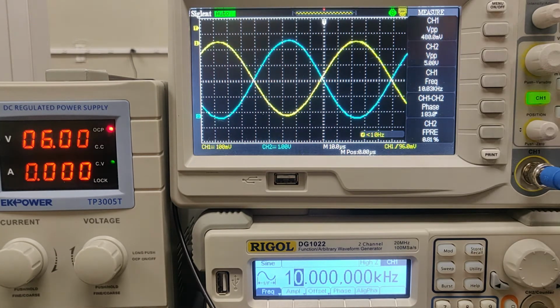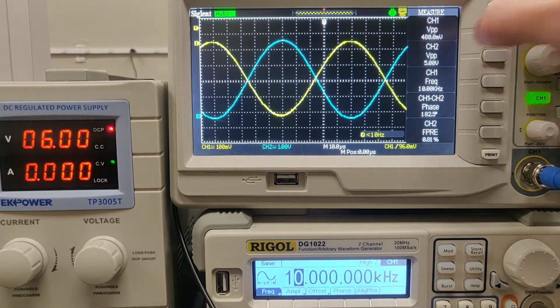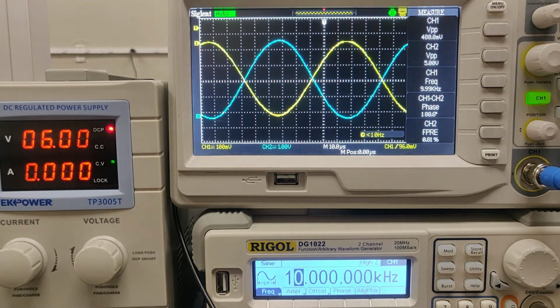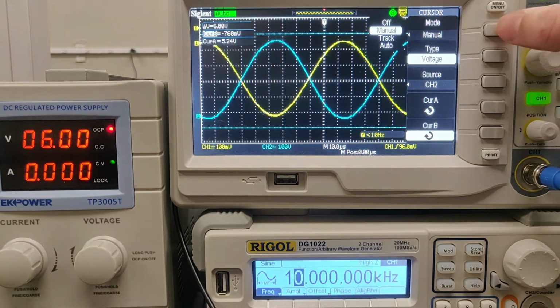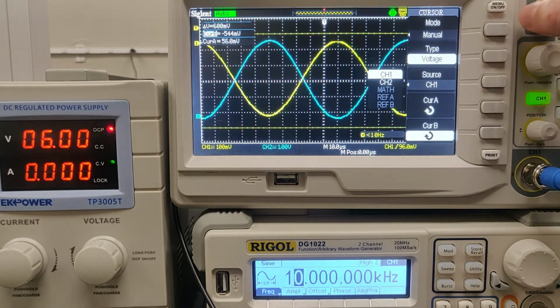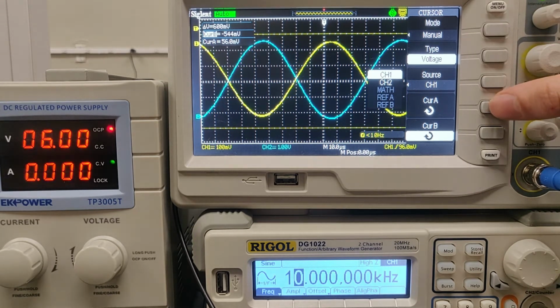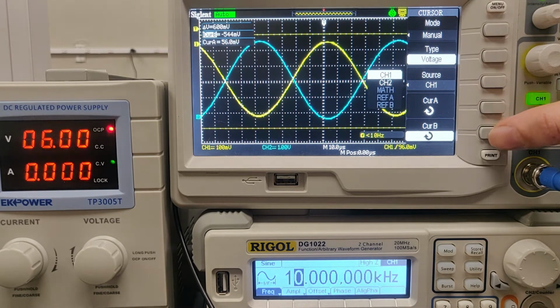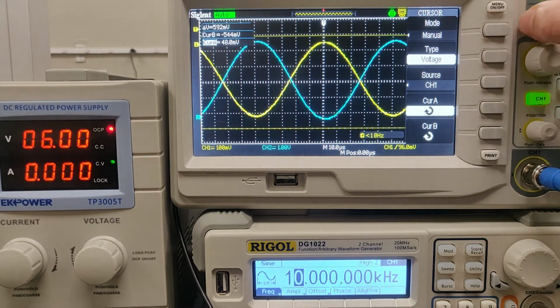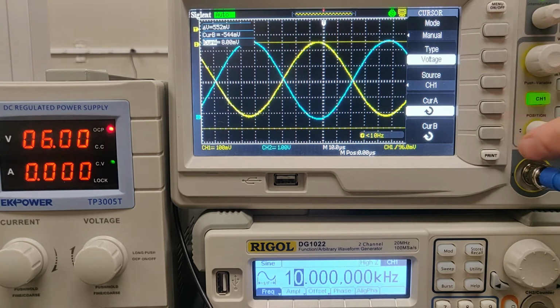our 2 waveforms. So we're seeing a 5 volts peak to peak for our output, and then somewhere, it's kind of moving around, so let's use our cursors to measure our peak to peak voltage for our channel 1. And again, it's primarily because it's a pretty small signal. Seems about right.